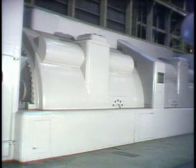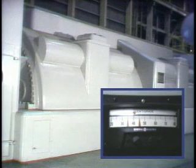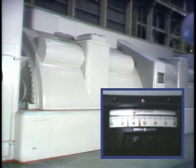In most cases, the temperature of the hydrogen inside a generator is maintained at about 105 to 110 degrees Fahrenheit, or about 40 to 45 degrees Celsius. To adjust the temperature of the hydrogen, an automatic control valve is used to increase or decrease the flow of cooling water through the hydrogen coolers.